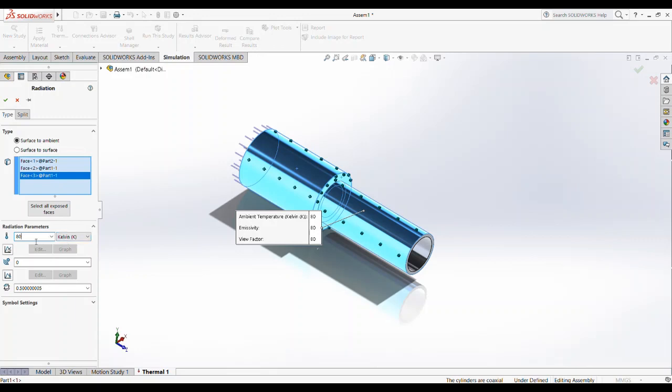80 Kelvin is what we would do if we put this in an environmental chamber and we want to recreate the coldness of space. We actually have a chamber that we run liquid nitrogen in, and the walls of the shroud inside this chamber are pretty close to 80 Kelvin. But if you do the math, that's pretty close to 0 Kelvin. I mean, the effect is very small. The difference between 80 Kelvin and 0 Kelvin when you do the temperature analysis is pretty small.